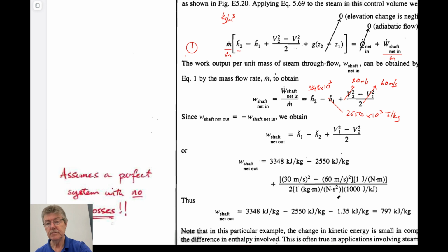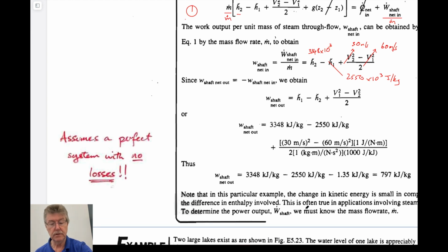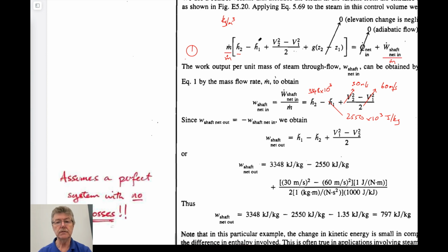And joules per kilogram and meters squared per second squared are equivalent to each other, and then you just do the math. These are just conversions in there to get around that. So no big deal. You just have to be mindful of the fact that you have to write things in the right order between upstream and downstream. So in is always incoming fluid, this is the outgoing fluid, and it follows all the way through here. And the enthalpy term includes the pressures that are in the system as well, which aren't otherwise given in this. It's just given as a combined enthalpy, which is